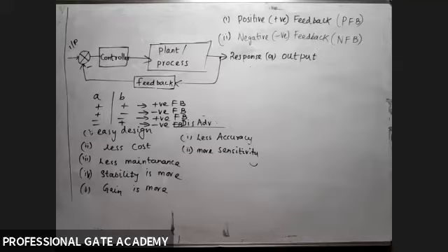In the textbook it is like that. If the textbook has a plus here, they say it that way. Here, if you have plus, what type of feedback? Positive feedback. If you have minus, negative feedback. But in GATE problems, if both are plus, then positive feedback. Both are minus, positive feedback. One is plus, another is minus, negative feedback system. If nothing is there here, by default we can take it as a plus.